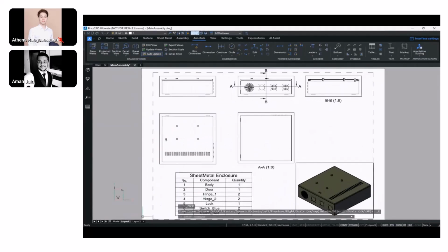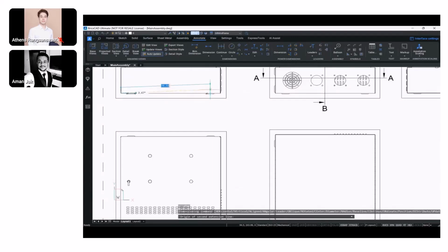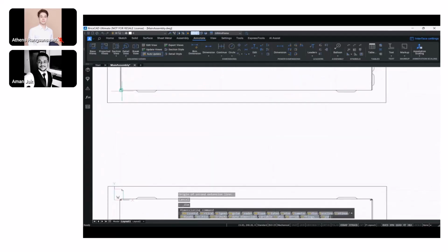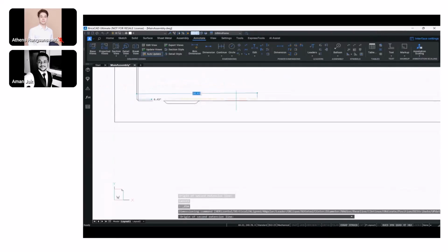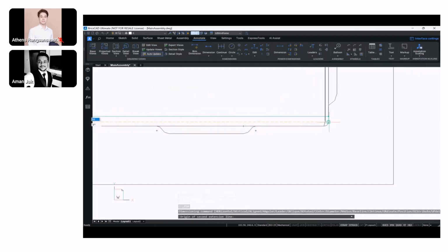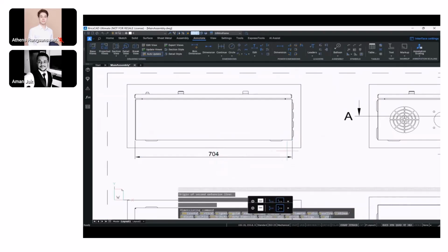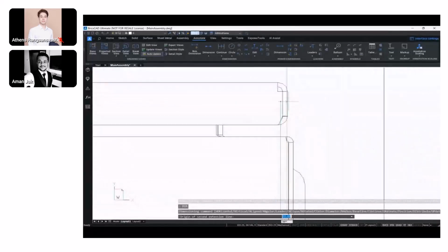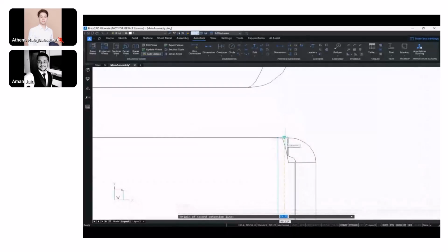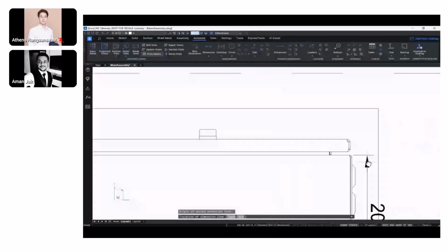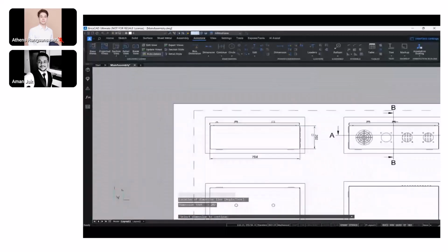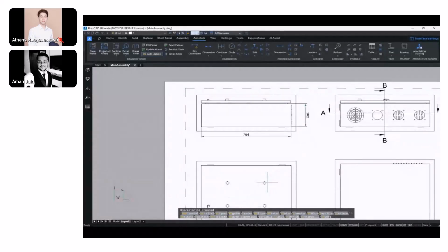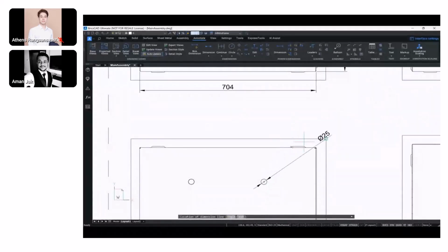Right. Last but not the least comes the dimensions. So let's say if we need to add dimensions, we can simply use the annotations in BricsCAD, very accurate dimension representation. And the best part is if we dimension this over here in layouts, and what I have personally seen happening is we annotate the entire thing in a 3D MCAD tool, and when we bring it inside a CAD environment, let's say it could be something like AutoCAD or even BricsCAD for that matter, when it comes from a traditional 3D CAD environment, it kind of loses all its intelligence, right? The dimensions act like lines, arrows, and text. It all comes exploded. There is no intelligence whatsoever associated to the annotations that we place inside a 3D modeling environment when it comes to the 2D environment.